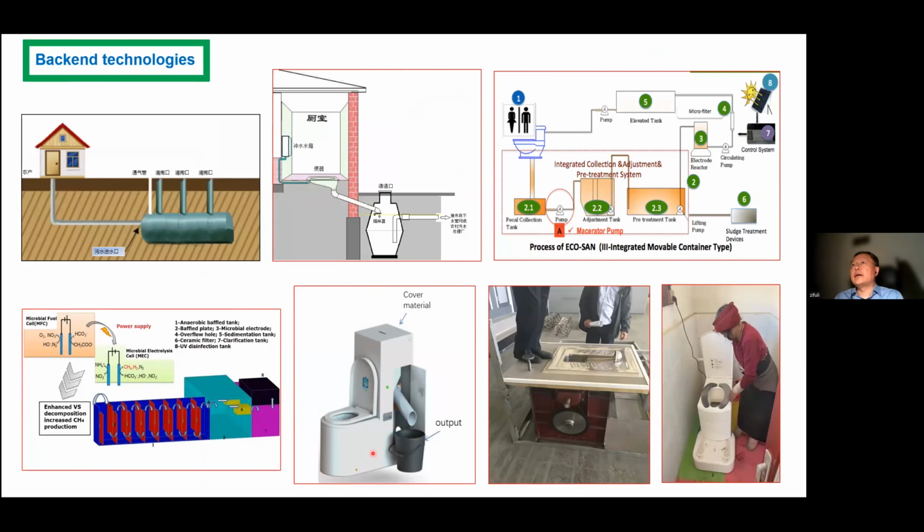And also for the treatment, you can see the different treatment processes. So this modified septic tank is not only three chambers. They also have five or six chambers. After the three chambers of sedimentation, the fourth, fifth, or sixth have some biological treatment units.